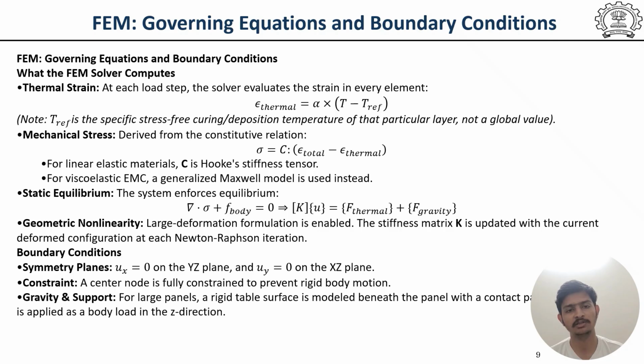For rigid materials, this stiffness tensor is the linear elasticity. But for epoxy molding compounds, which creep and relax over time, we use the generalized Maxwell model to capture its viscoelastic behavior. To balance these forces, the system enforces static equilibrium. The stiffness matrix times displacement equals the thermal forces plus the gravity.